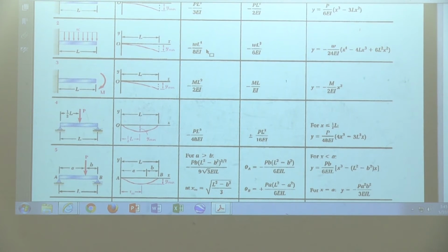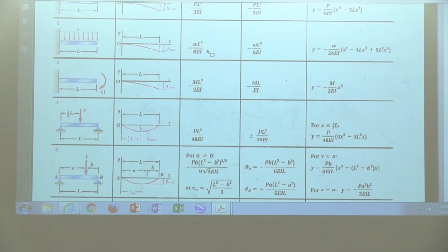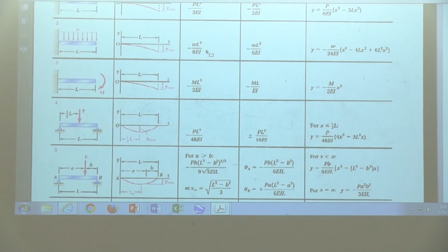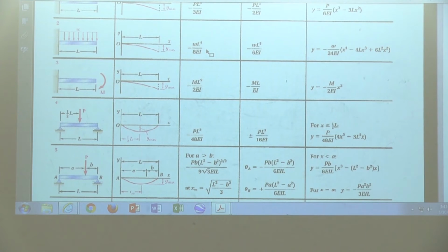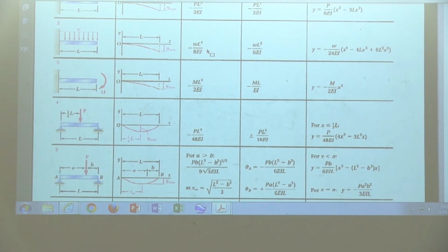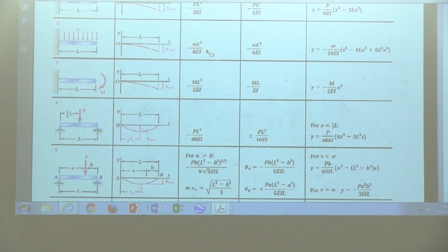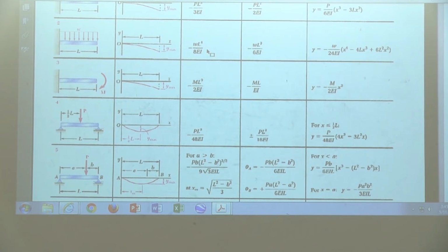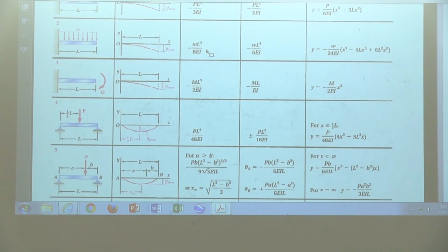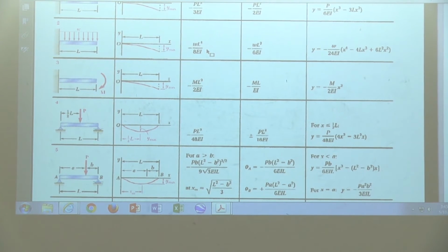Again, one more time. Since this YB pushes beam up such a way at this point you have no deformation, when you break it into 1, 2, 3 system, the sum of the Y at the same point B must be equal to 0. You cannot add, this is the mistake a student makes sometimes. They add this maximum to that maximum to that maximum. That's irrelevant. Everybody see that that's a wrong approach?